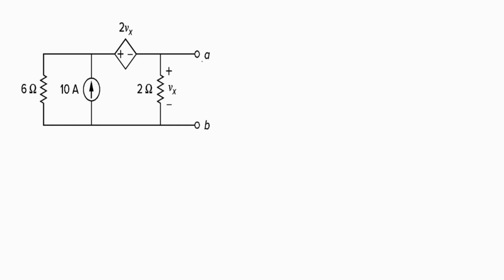So, as we always do for Norton's theorem, we are going to identify the output terminals. In this case, this is given as AB, and there is no load connected here. If there were to be a load connected, we would remove it and then we would short circuit it. Then we need to compute the short circuit current ISC flowing between the terminals AB.